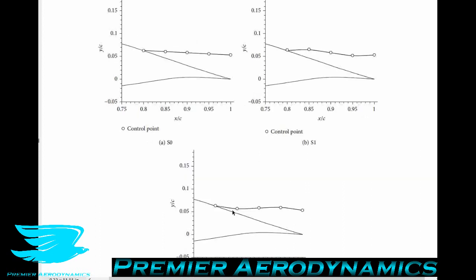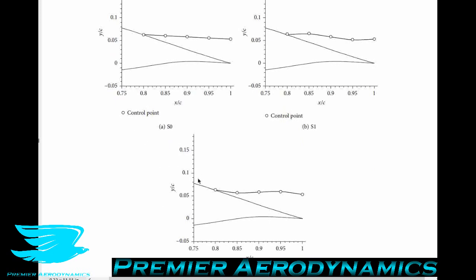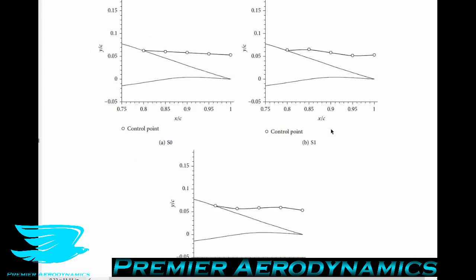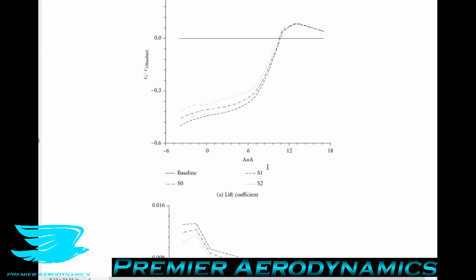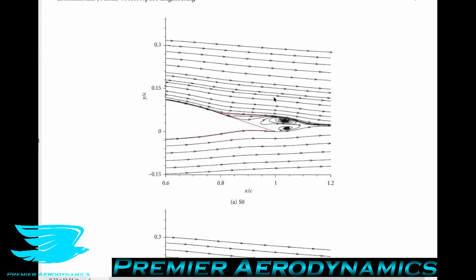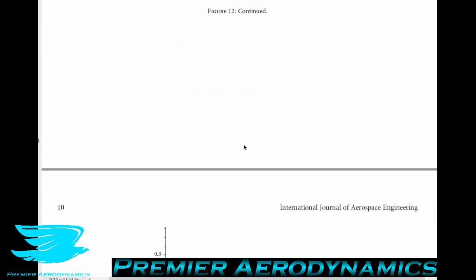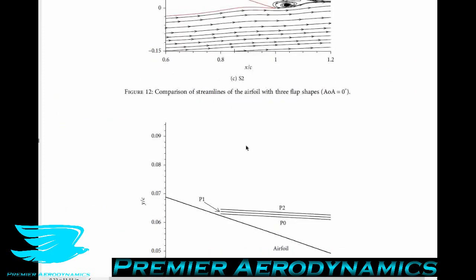And the opposite is true for the S-shaped one where we have the trough first, then the peak. So the flow may come down, stay attached quite nicely. Then when we get to this point, it then detaches a little bit and we get a smaller wake, but there is still a bit of wake here. So that's why I think we do get these changes based on these different shapes, which weren't that clear in these streamlined figures here because I'm not sure what's going on with these labelings, if it's accurate or not. I don't think it is accurate. But that's what I think is happening.